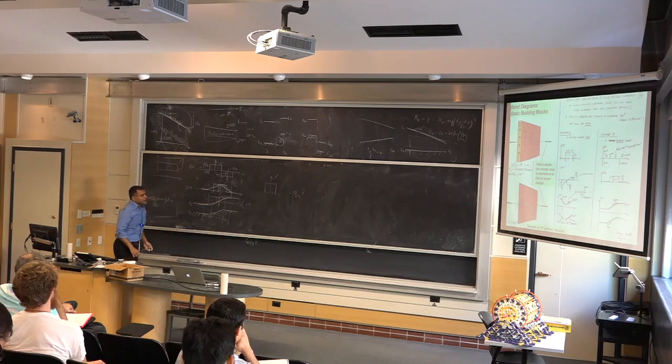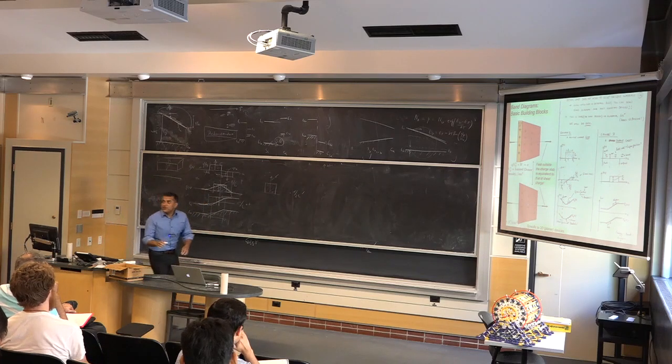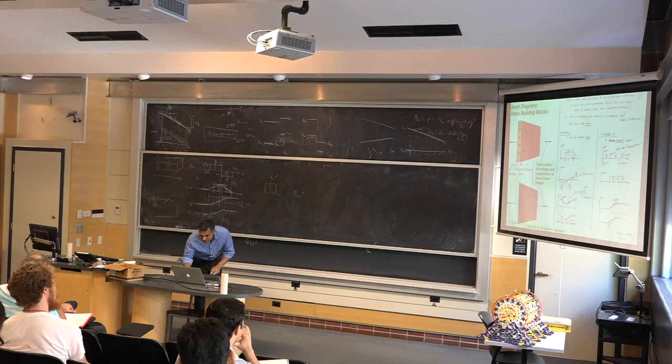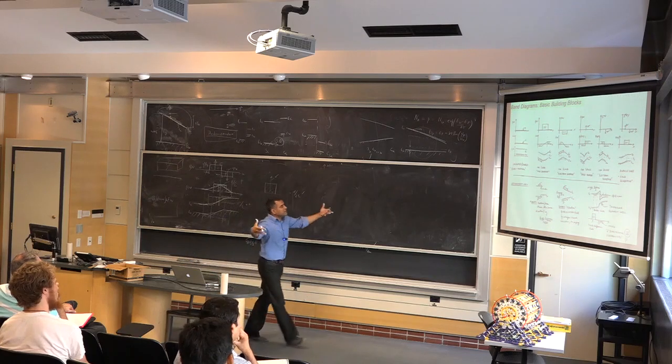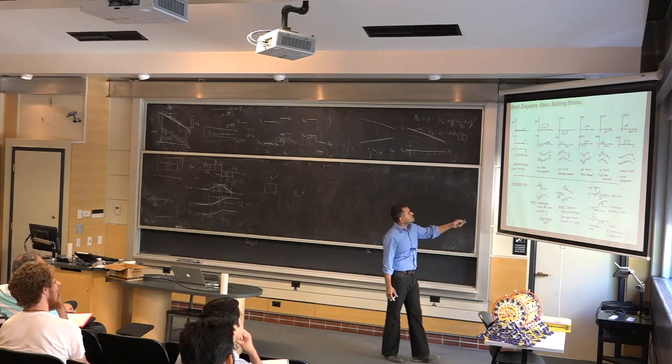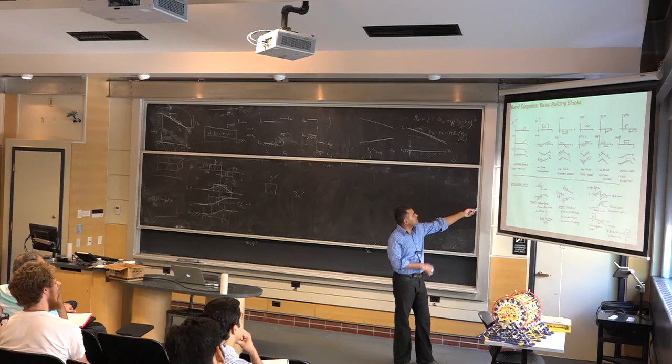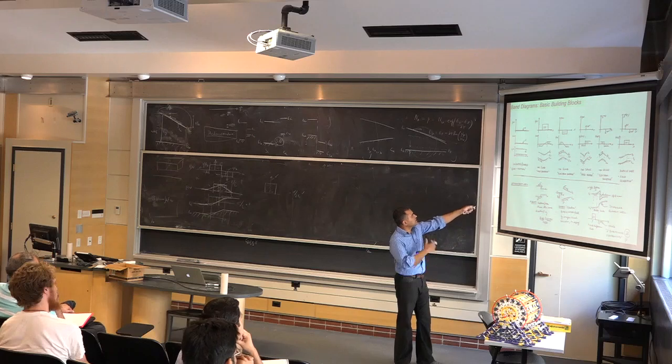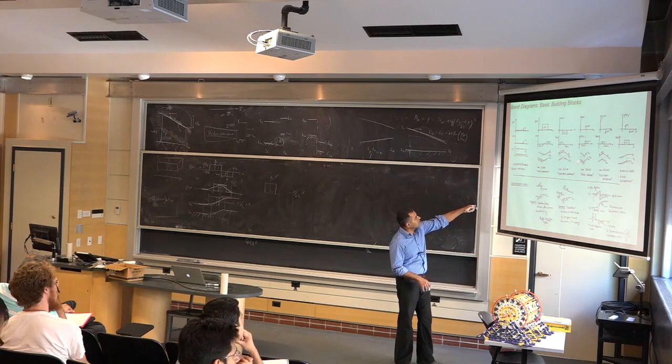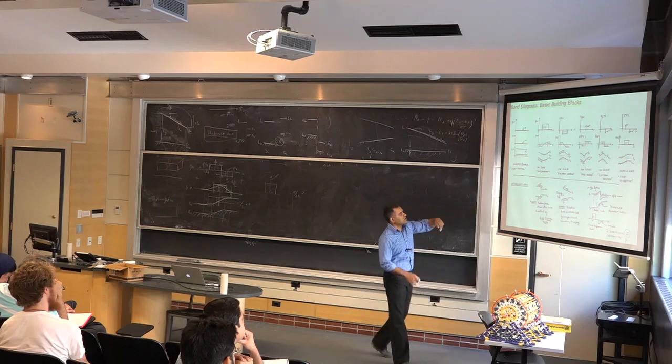Okay, so I think we are getting close to the end, and you can now play with it and create all these other structures. You have flat bands when you have no doping. We just showed that if you dope it positive and negative, you get a hole barrier. You can get an electron barrier by flipping the direction of the charges. You can make triangular ones and all this sort of thing.